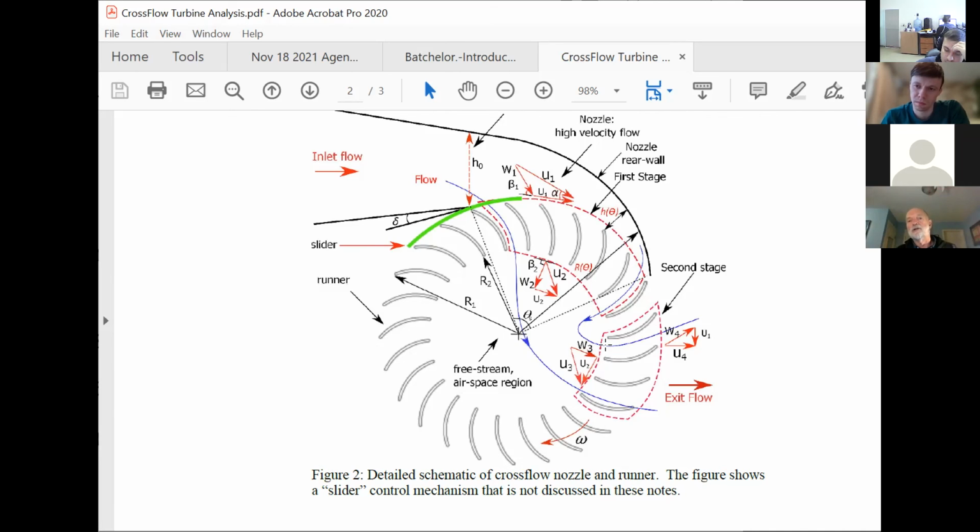And cavitation occurs when the local pressure in a water flow is less than the vapor pressure. And what that means is that you effectively get bubbles formed in the flow. And those bubbles can cause noise, they can cause vibration, and they can damage the blades. And a lot of the off-design performance of turbines like Francis turbines is really about issues associated with cavitation. And yes, I think the same thing is likely to be the case with Crossflow turbines.